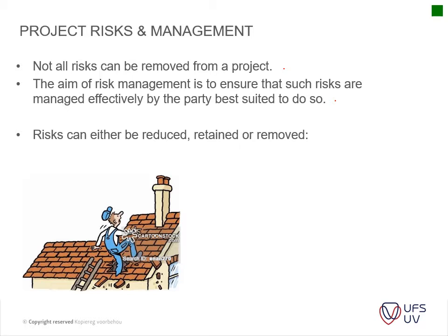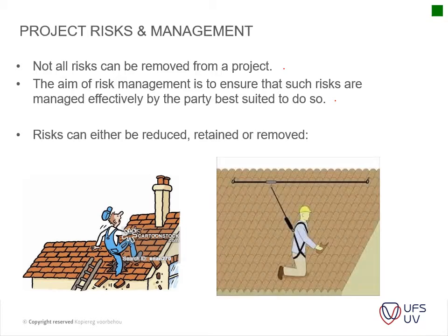Especially on a steep roof, you can have accident happen very quickly, and simply using a harness, you can improve the safety of the personnel on site considerably. Obviously, roof installer specialists will be more equipped to have these type of materials, safety harnesses and PPE available.